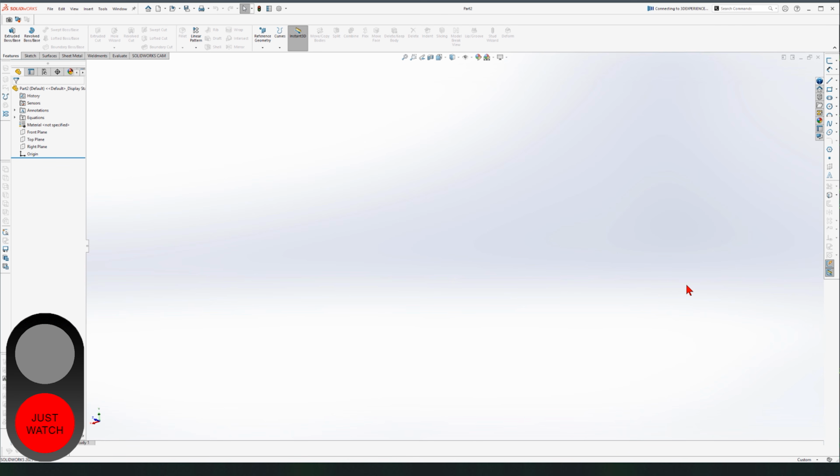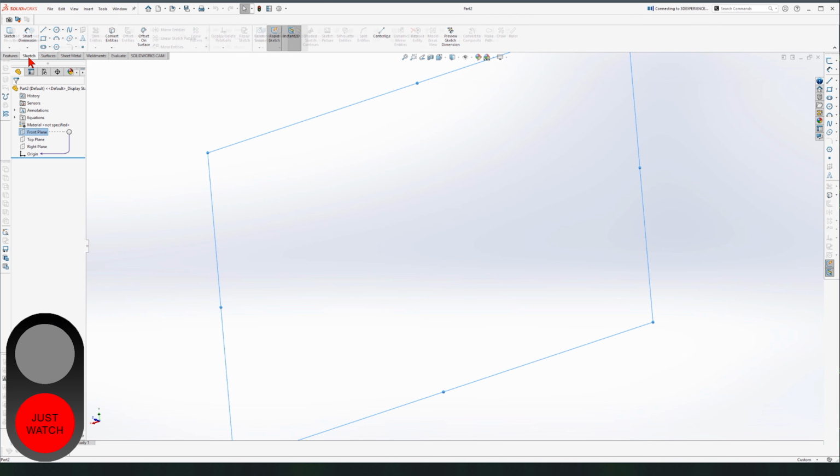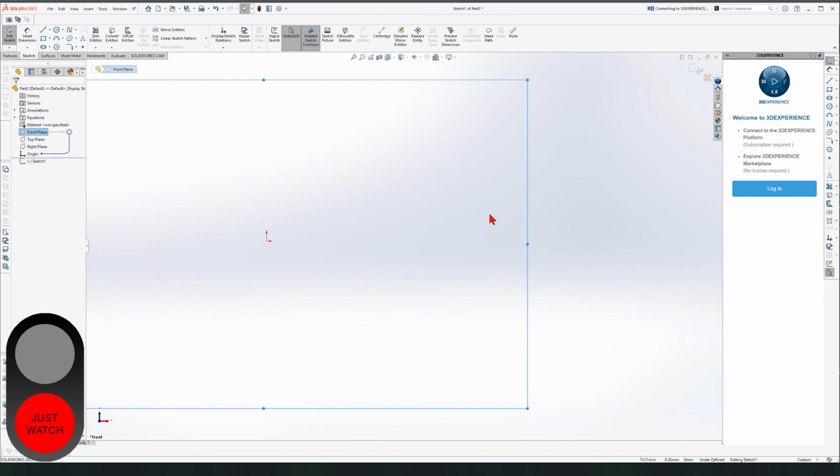So our steps are already predefined. Define a plane, draw your 2D sketch, turn it into a 3D object. Okay, given we are going to start with a rectangular cuboid box, this is pretty easy. Let's say we want to begin our journey by drawing on the front plane. So one click here, we go to the sketch tab, as I said, and we want to start sketching. We can either draw on the tool directly, which activates the sketching mode, or we can just click on the sketching mode to make sure we are looking at our front plane perpendicularly, just like right now.